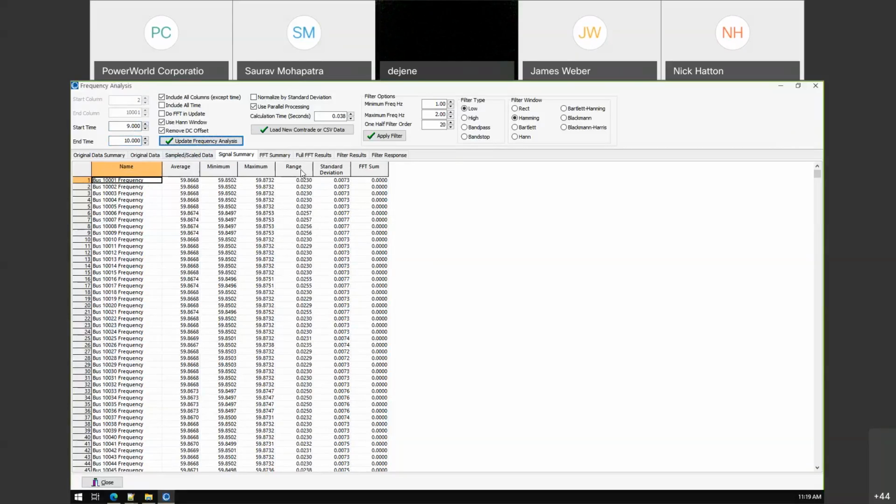If you look at the range here, you can rank it from smallest to largest, and it gives you the ability to see which buses, in this case frequency, are still oscillating. Within the last 1 second, it looks like these buses are oscillating, plus or minus 0.2541, but many of the other buses in the case are going towards a new steady state. As you can see, these values are going towards 0. Going towards 0 is good because that means you're reaching a new steady state. Otherwise, you are not. So this is one of the new features that's been recently added.